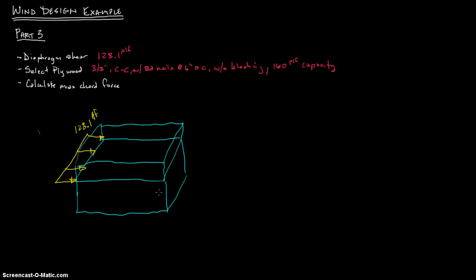If you remember, we took that and looked at it like a deep beam. So here is the beam right here, like an I-beam or a wide flange beam. That's what I mean by look at it like a really deep beam. It's a 60-foot deep beam. There's your flange, and the web is the diaphragm itself.